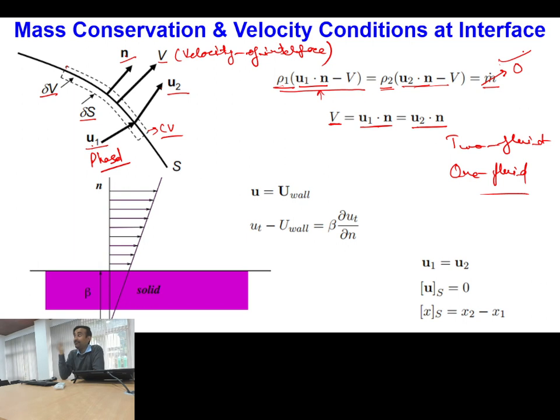Likewise, whenever we define the interface between two immiscible fluids, we assume that our interface is nothing but a sharp interface at the macroscopic or mesoscopic level. Of course, if you look at the microscopic level, at the scale of a few nanometers, you may find that near the interface there is some portion, as I told you earlier, where molecules of both phases are present. That is the interface. But at the macroscopic level, that nanometer thickness of the interface is negligible, so the interface appears to us as nothing but a sharp boundary.